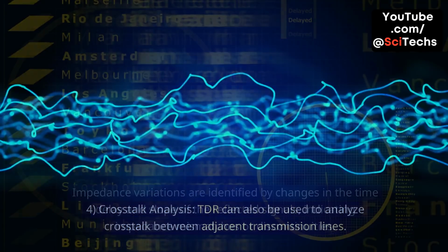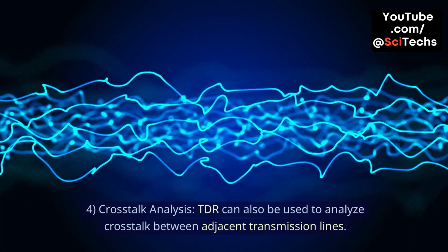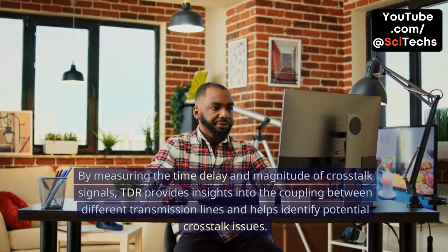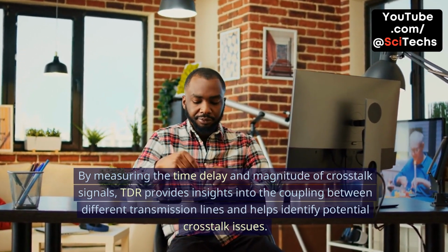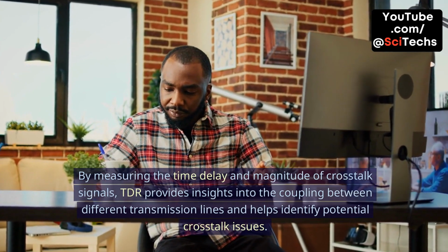discontinuities. 4. Crosstalk analysis. TDR can also be used to analyze crosstalk between adjacent transmission lines. By measuring the time delay and magnitude of crosstalk signals, TDR provides insights into the coupling between different transmission lines and helps identify potential crosstalk issues.